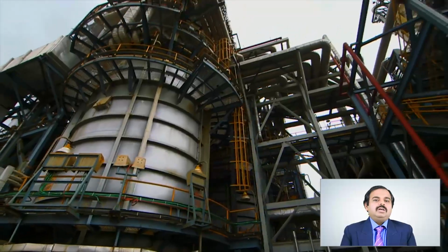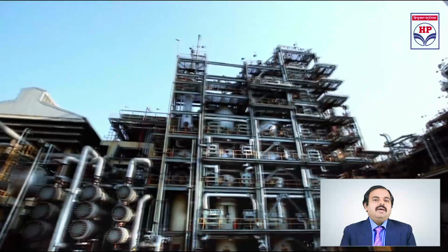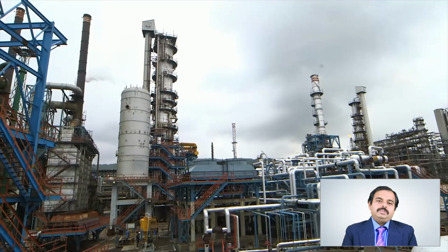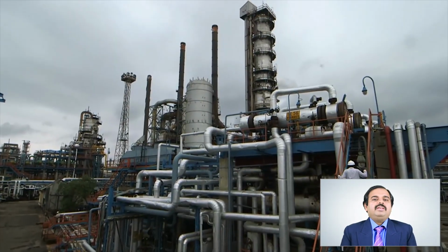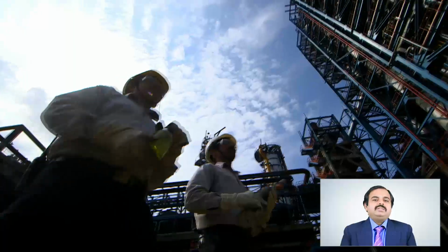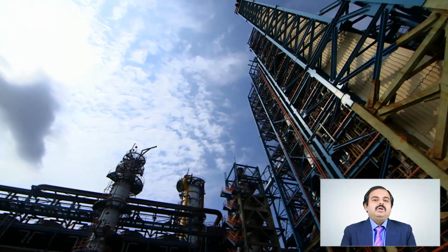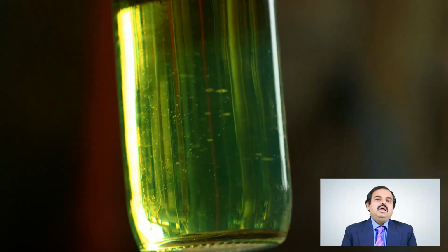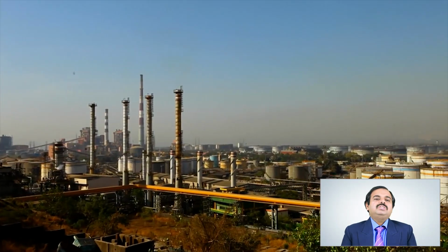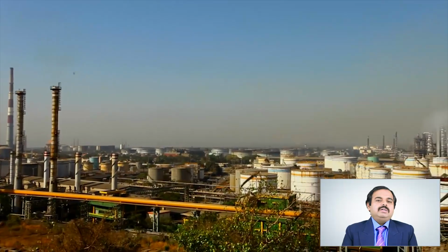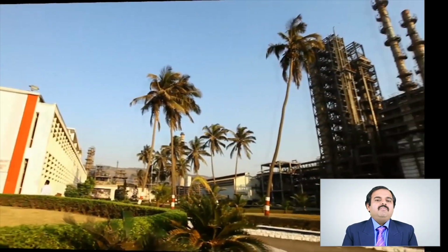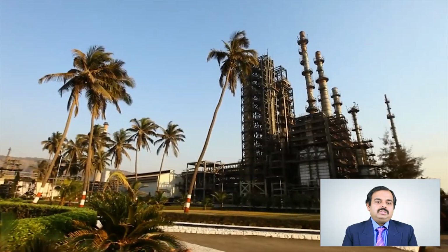The distillates undergo solvent extraction where NMP is used as a solvent. The aromatics are extracted and the raffinates are further subjected to deep hydrotreatment and catalytic dewaxing known as MSDW. The distillates are then fractionated and treated for removal of sour gases.